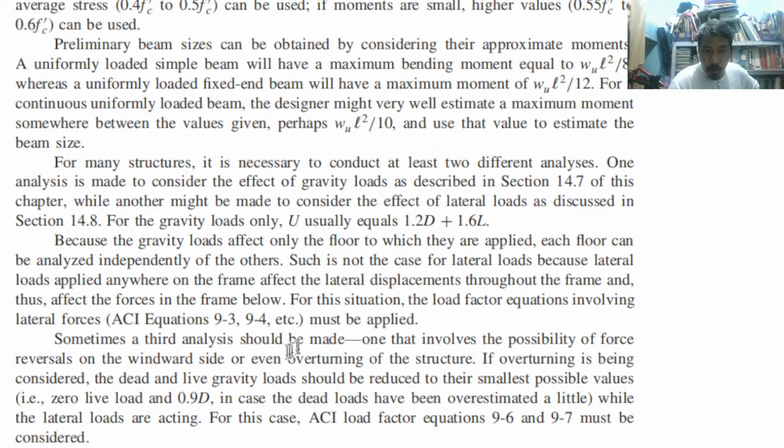Sometimes a third analysis should be made, not only two analyses. So, vertical load, lateral load, and a third analysis, one that involves the possibility of force reversals on the windward side or even overturning of the structure. Take note of the word overturning. You will encounter this in other design subjects. This is a design technical term.